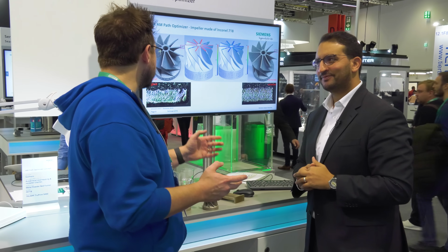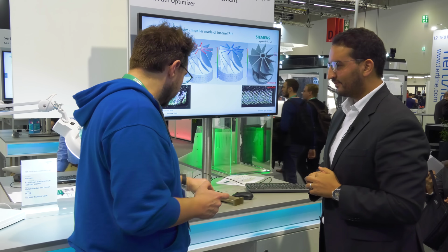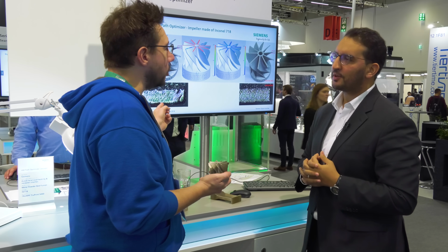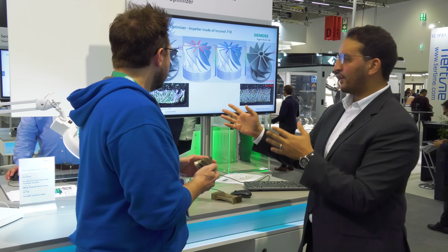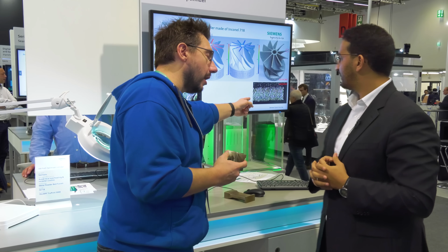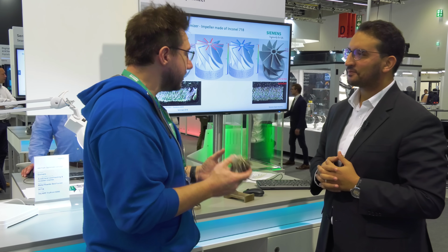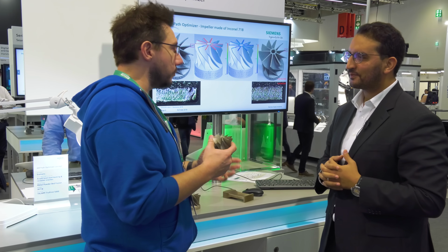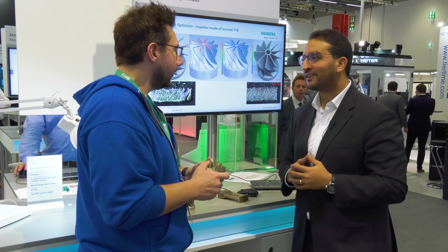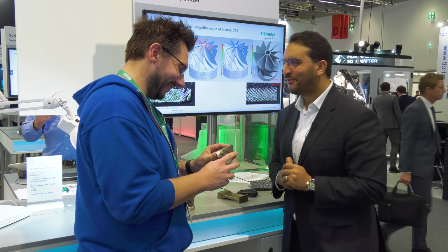Oh, I see what you're saying. So a part like this, while it still may visually look okay, this would never be qualified. It will not be qualified. You couldn't use this in production. No, you can't. Because without getting too much into the detail, the microstructure of the material here will be different than here, and quality therefore. And this part, because it's been corrected and it's consistent, could now be used in production. Absolutely. And we are doing this with our internal factories. We are testing this solution, and we're hoping next year to industrialize additive manufacturing, hopefully.